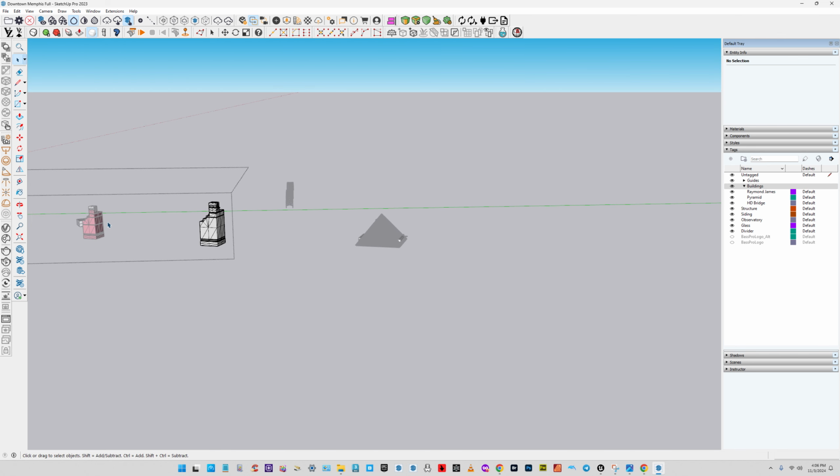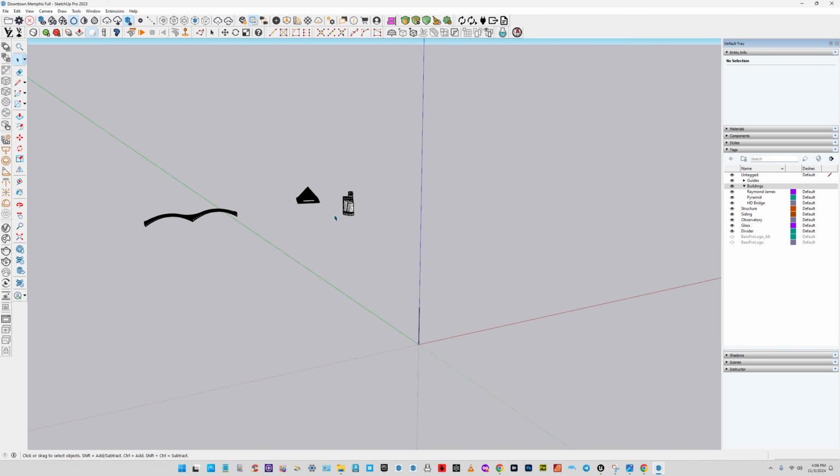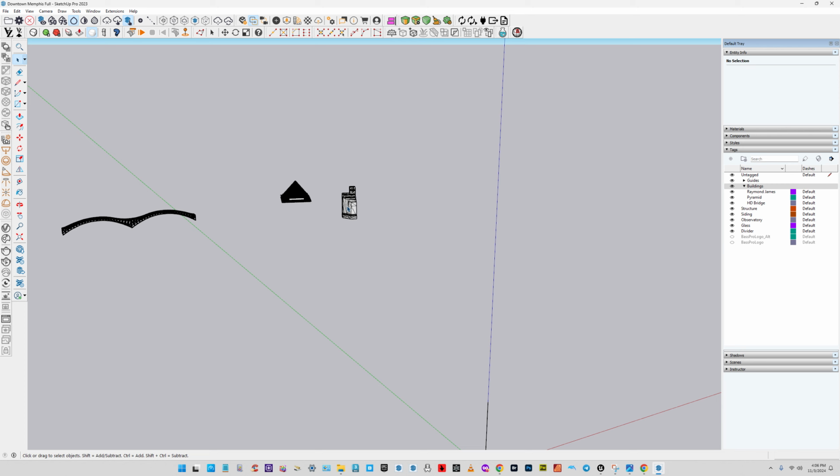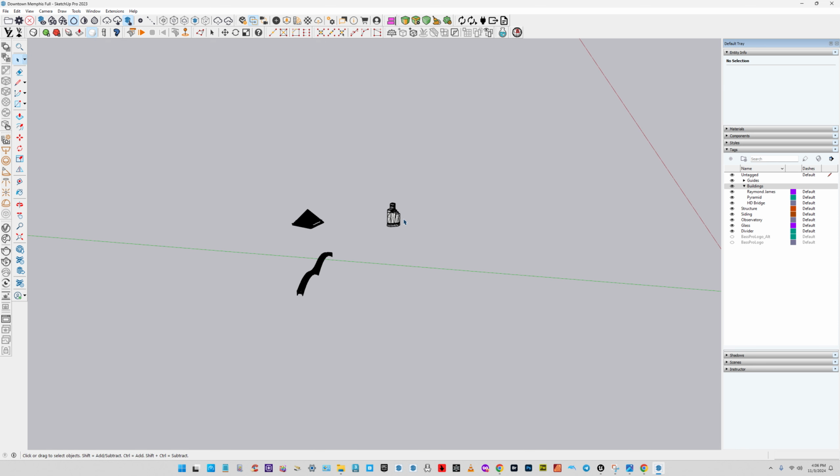So don't do an STL import because you're going to get a bad model. Do an OBJ export and scale down to 0.5, right?